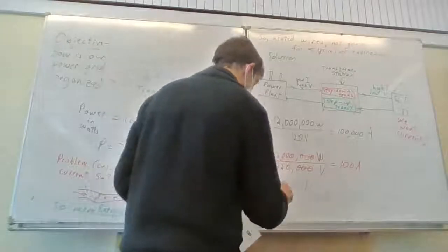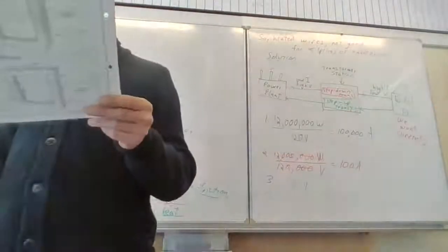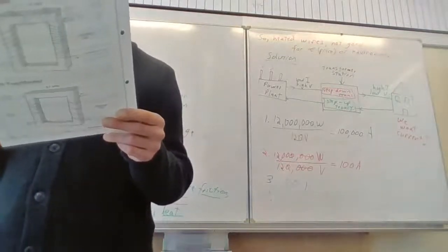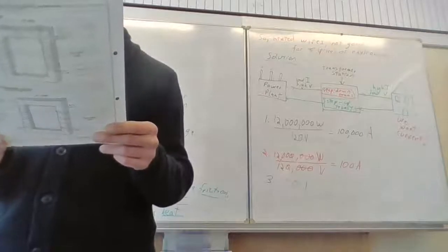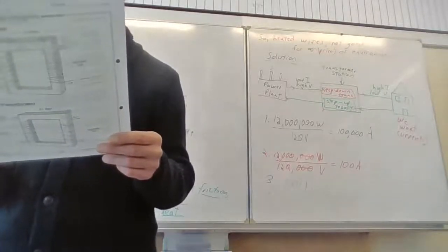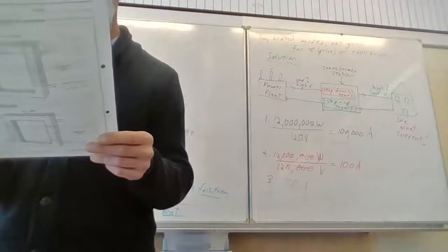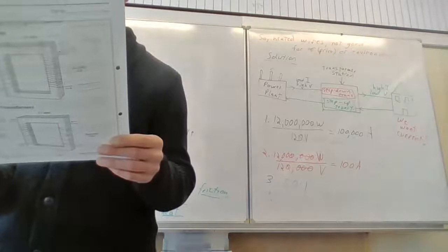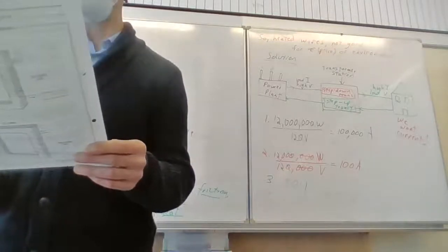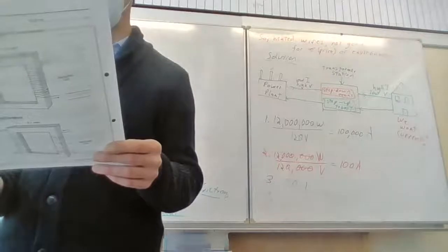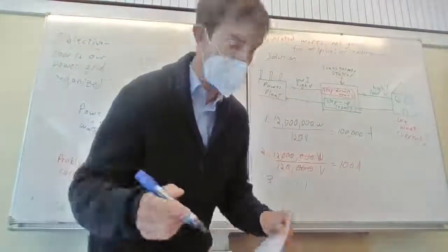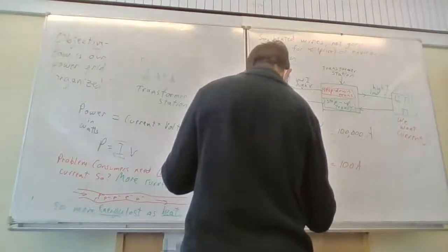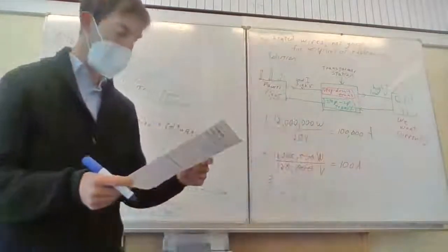Okay, number 4, yeah? Going the other way, right? So can you read for Sina, please? What ratio of primary turns to secondary turns should be on the transformer to step 2,400 volts down to 120 volts? That we could probably do mentally. Aaron? 20 to 1? Good job. So she's got it, 20 to 1. And it's another step down, isn't it? Because I'm going from high to low voltage, aren't I? So 20 to 1.